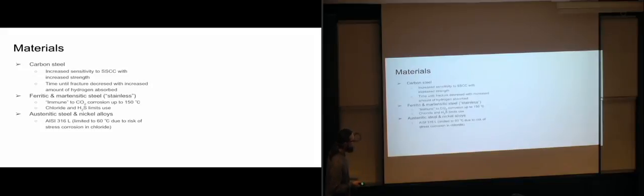And in a chloride condition, it basically means that we have to make sure that the temperature is less than 60 degrees Celsius. So if we are in a chloride condition, for example, in the well flow, we have chlorides present, we need to make sure that our well flow keeps the temperature lower than 60 degrees Celsius if we are going to use the 316L.